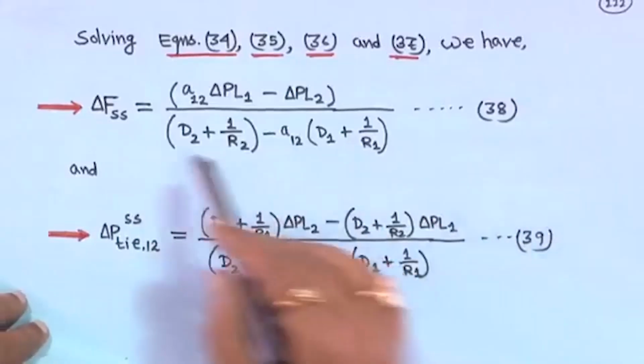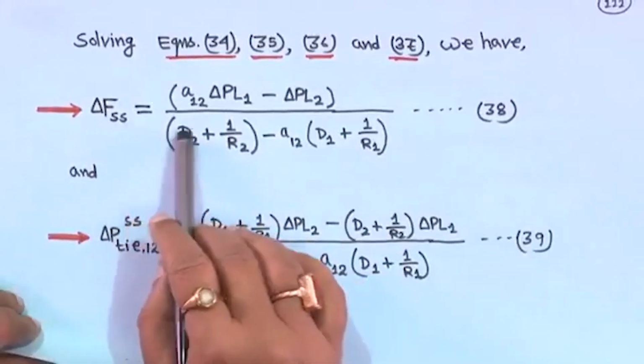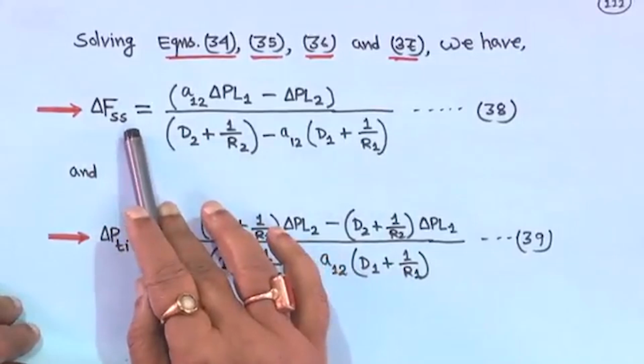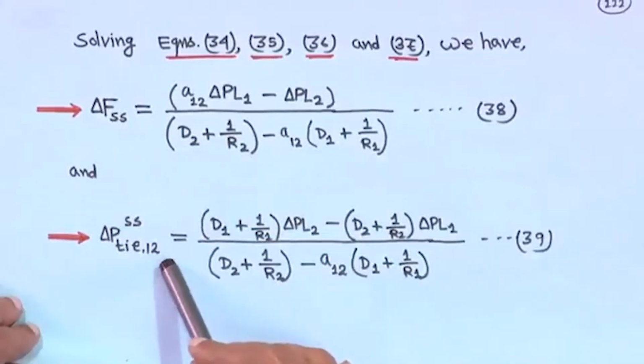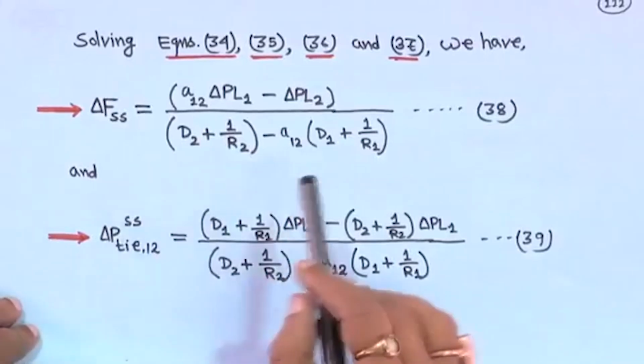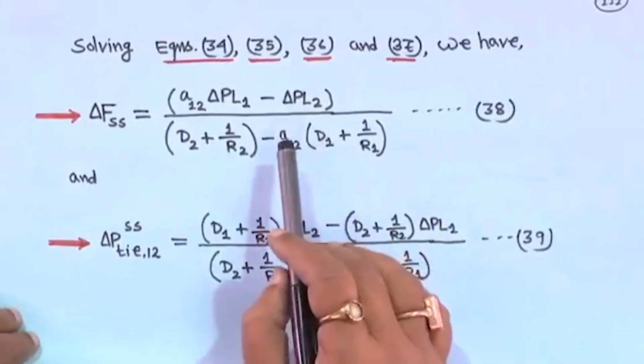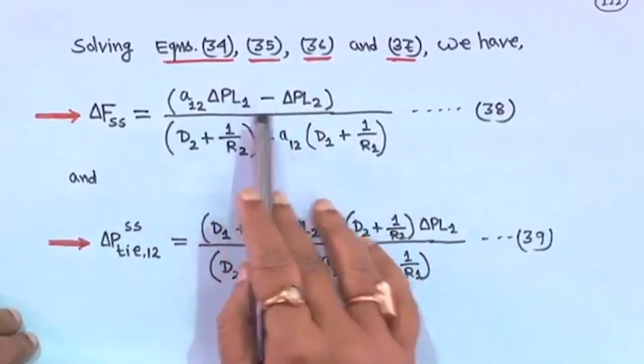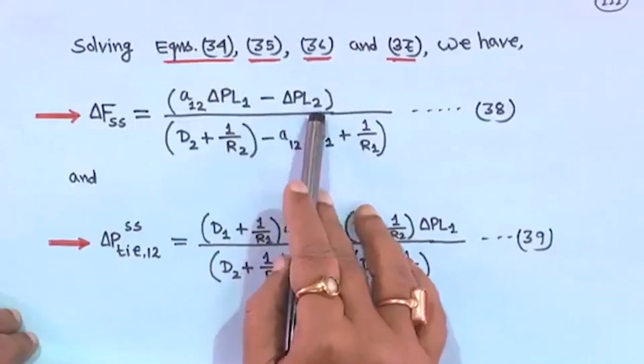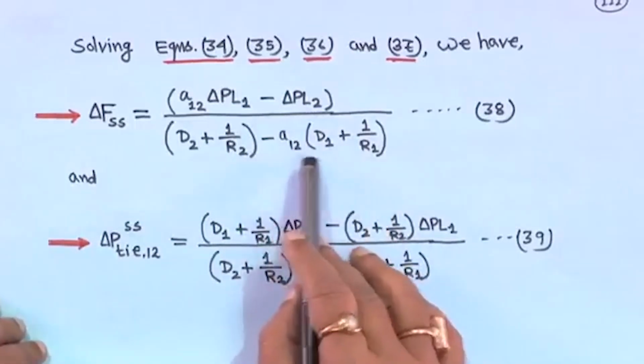Okay. So, we have seen the expression for a two area interconnected system: this is the frequency at steady state, and this is the tie power flowing from 1 to 2, the steady state values. And we have seen one special case when the disturbance was in area 1 and in area 2 it was 0, and the area capacity was the same for both the areas.